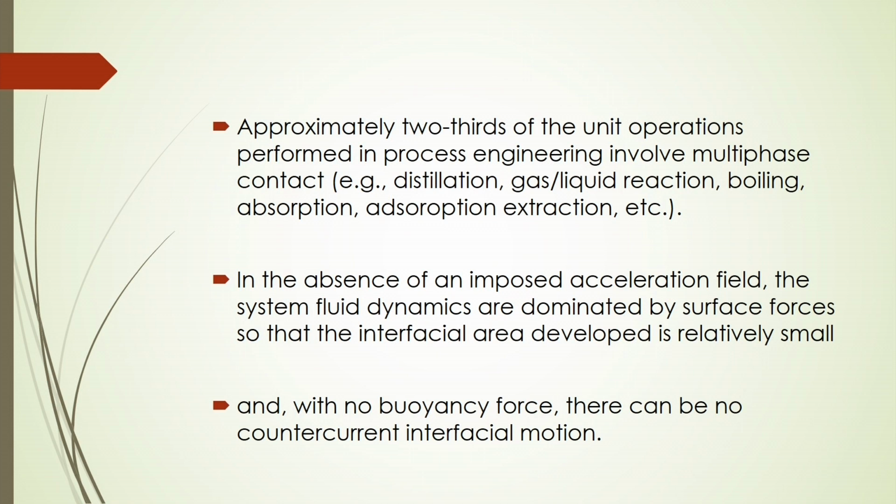Now, in a pool of liquid, if you supply more bubbles, the advantage is that you can get more surface area, and if you control the bubbles to flow for a longer time in the liquid, you can get more mass transfer also. So, you can intensify the mass transfer process based on the increase of surface area as well as the residence time of the bubbles there.